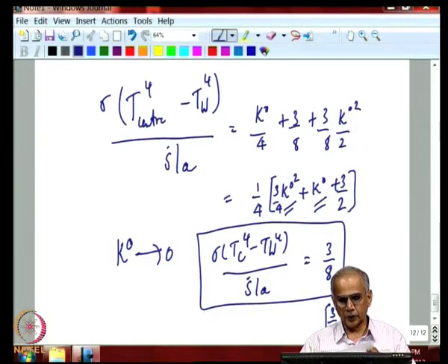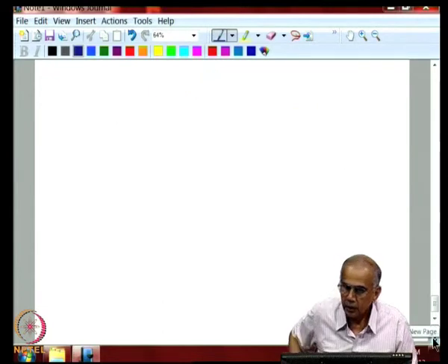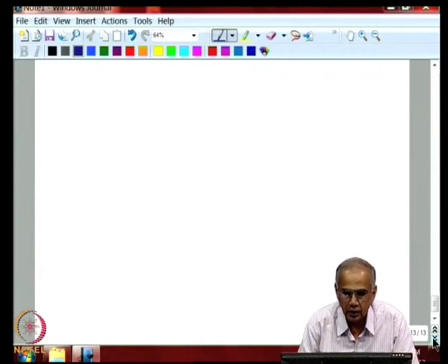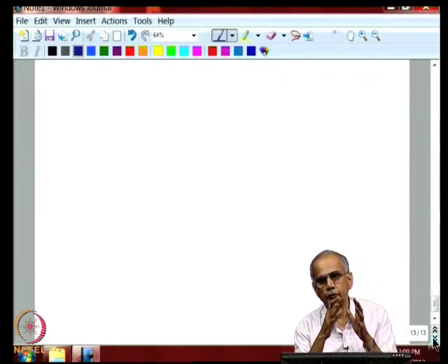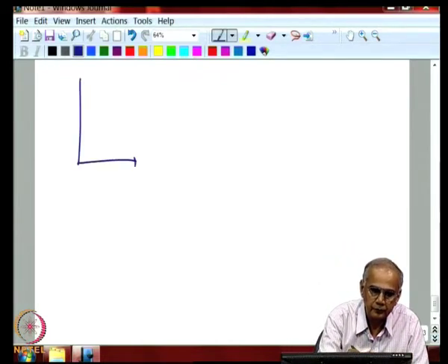the gray gas approximation is not a useful approximation for radiative transfer in gases in many real life situations, because most gases which absorb and emit radiation are not gray gas. In most gases, the absorption coefficient varies substantially with wavelength.